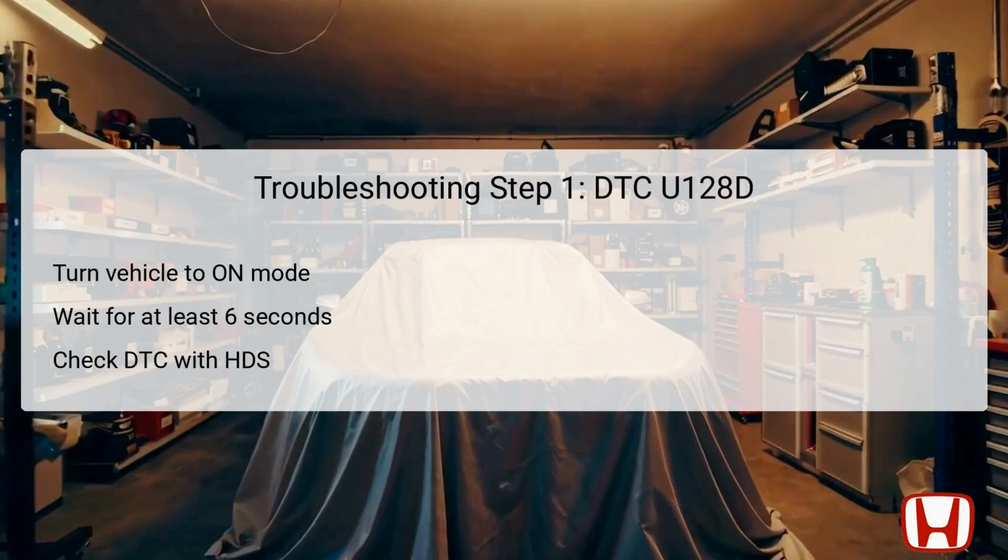The first step in troubleshooting DTC U128D involves switching the vehicle's ignition to the on mode. This action primes the electrical systems and allows the vehicle's onboard diagnostics to start properly. After turning the ignition key, it's essential to wait for at least 6 seconds to give the vehicle's systems ample time to initialize and perform self-checks. During this brief waiting period, the climate control unit and gauge control module can coordinate and try to establish communication.